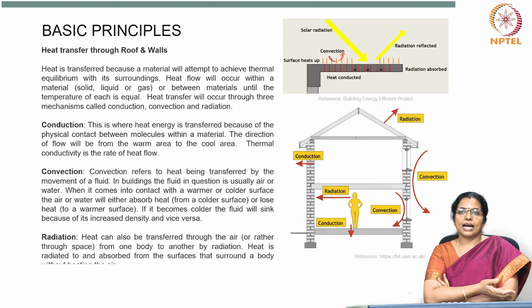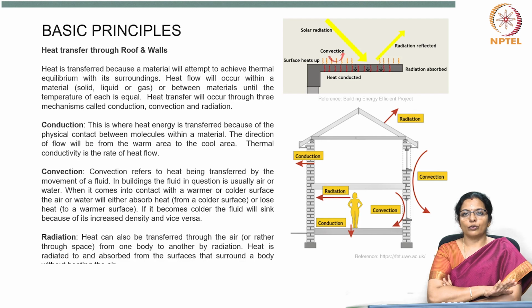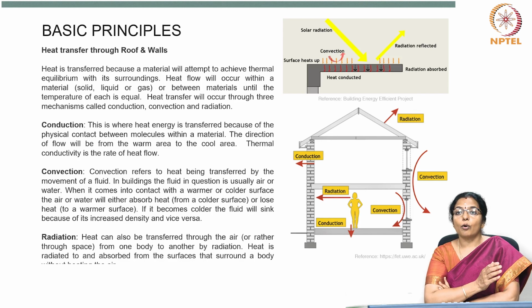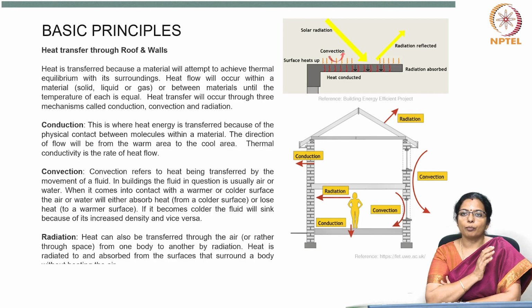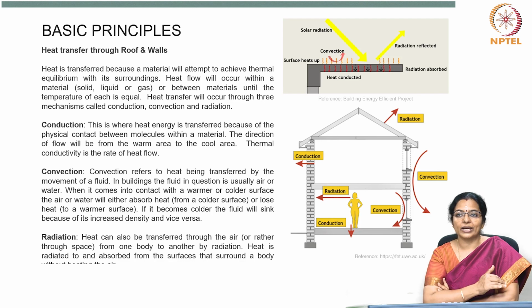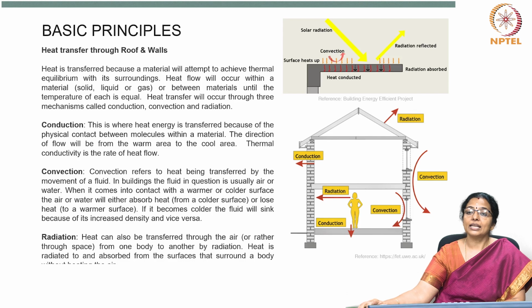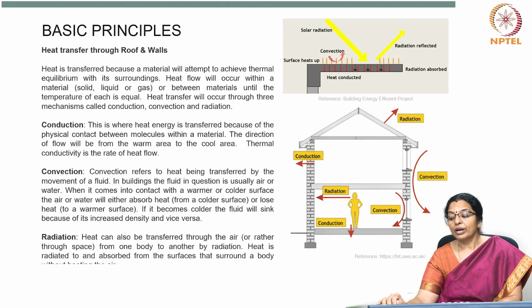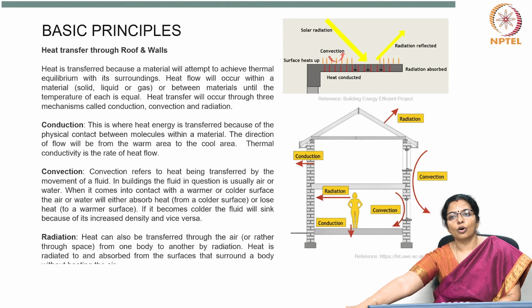So, if a person stands in bare feet on a concrete floor and then a wooden floor, the body will sense the different rates of heat flow. That is, heat will be transferred from the body to the concrete more quickly than to the wooden floor because concrete is a better conductor. The concrete floor will be less thermally comfortable than the wooden one, although in fact a ground bearing concrete floor usually offers better thermal insulation.